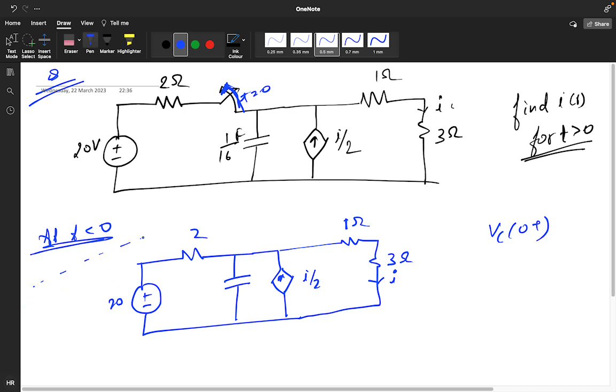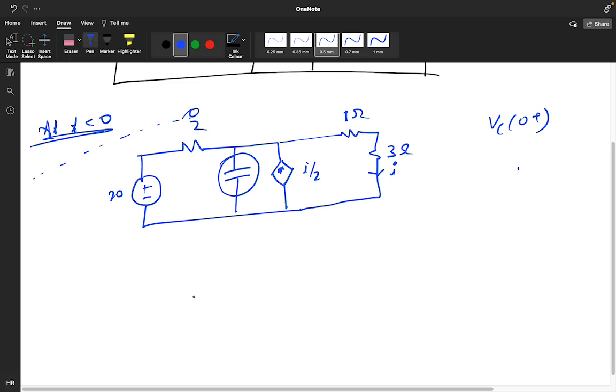Means it was going like this, going like this at an infinite position. So that means my capacitor was open circuit. So if my capacitor was open circuit, so I have something like this, positive negative 20 volt. Sir, what if we consider t is greater than 0, then also the capacitor will be...